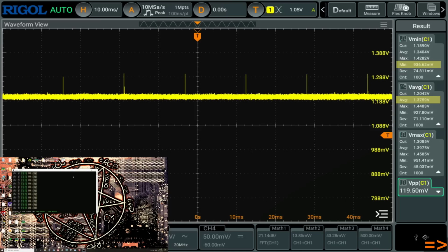Yeah, so I was a little low. Evidently, I should have punched in 1.42 instead of 1.4. Actually, I should have punched in 1.43 volts, because we're 30 millivolts below what I was aiming for. But if I move the mouse, we don't really see a significant increase in undershoot. So yeah, this is actually a really helpful feature.